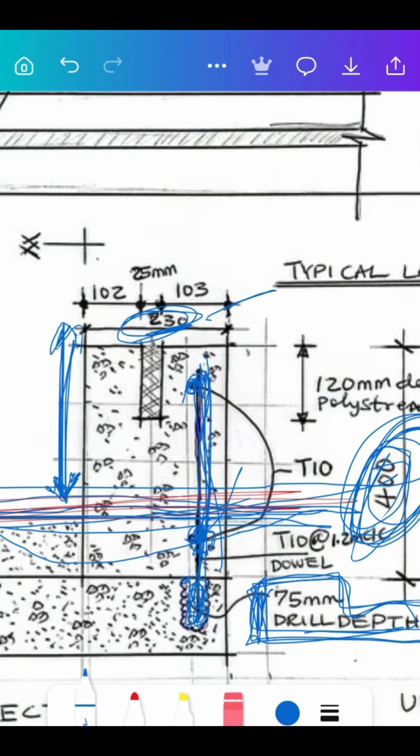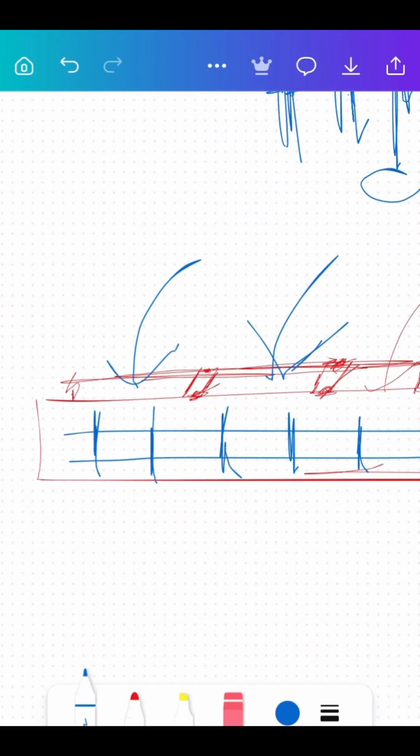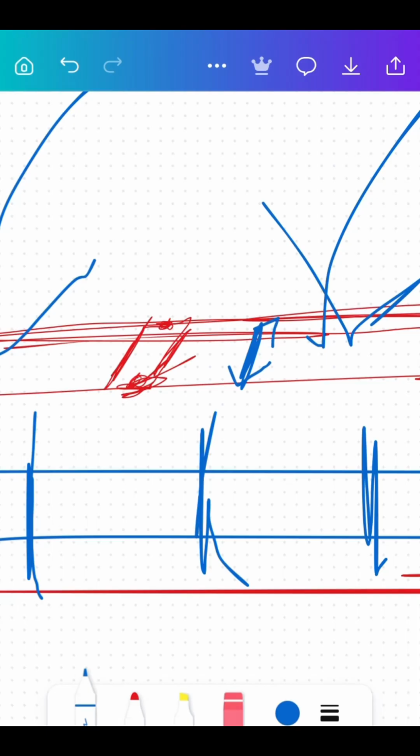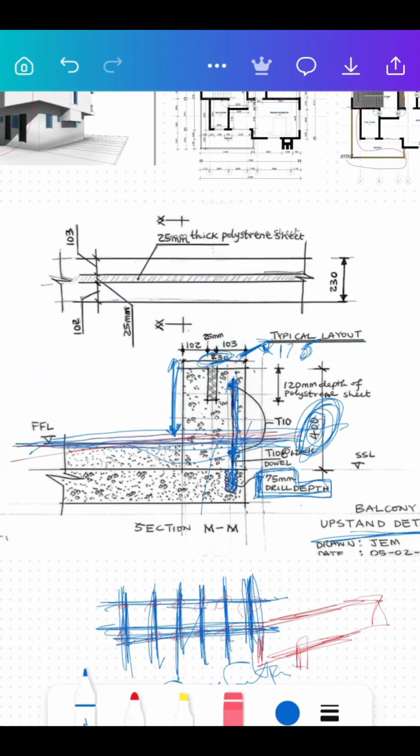Okay, we made a change to this. It's not 23 centimeters. Now it's about 17.5. That was a later change. We already started casting, but they gave us a change which makes it 17.5. So actually now the width of this concrete is 17.5. Your formwork has to respect that. If you take your tape and measure the formwork from board to board, it has to be 17.5 on the dot. And if you're measuring the height of the formwork, the carpenter will call the wood, it has to be 40. So this ensures that the concrete meets our height and width specification based on the plan.